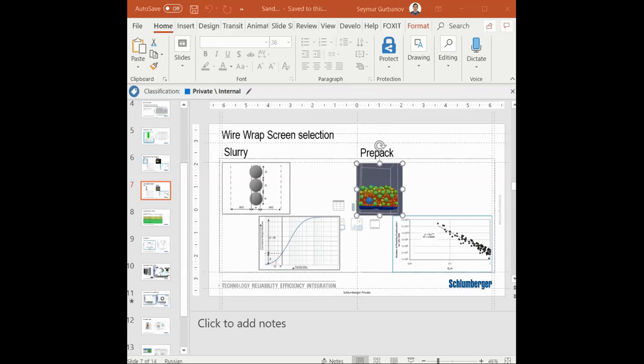If you're talking about some kind of turbulent flow where your sand will separate, the sand has to go somewhere. So it will settle inside your wellbore or drop to the shoe. So eventually it will build up to a certain level when it will create problems. But so far, I'm not sure about any other ways except the screens.